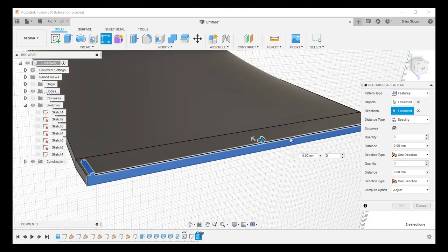And we can start to pull this out and you can adjust the spacing. So this gives you a visual sense. 2 millimeters is probably too far away. So let's try to go maybe 1.5 millimeters. That looks good. And then how many do I want? You can switch over here and, oops, nope, wrong one. 1.5, there we go.